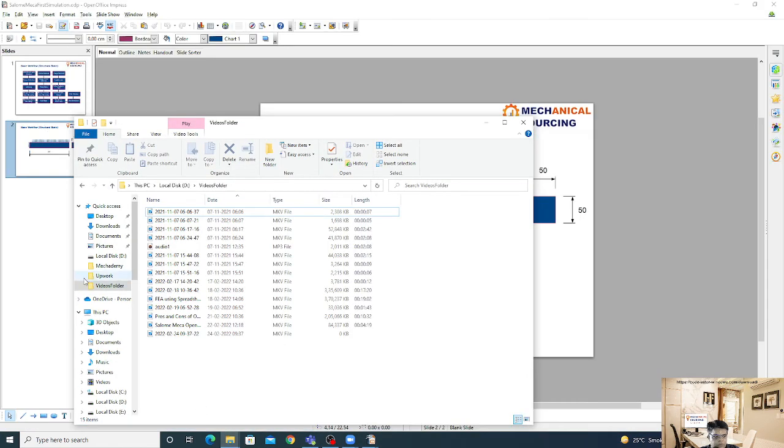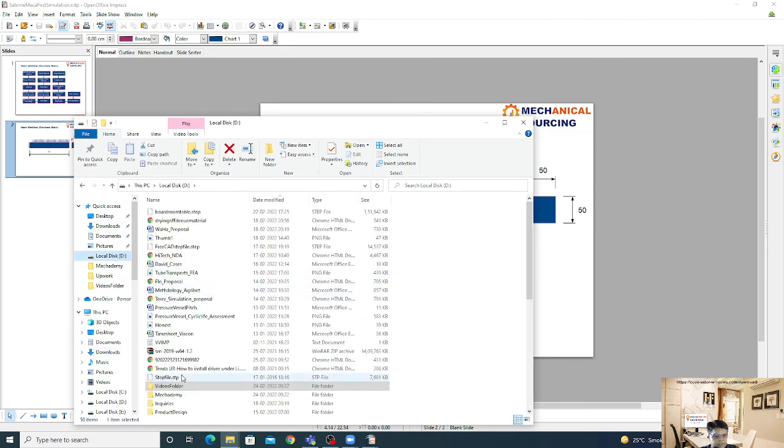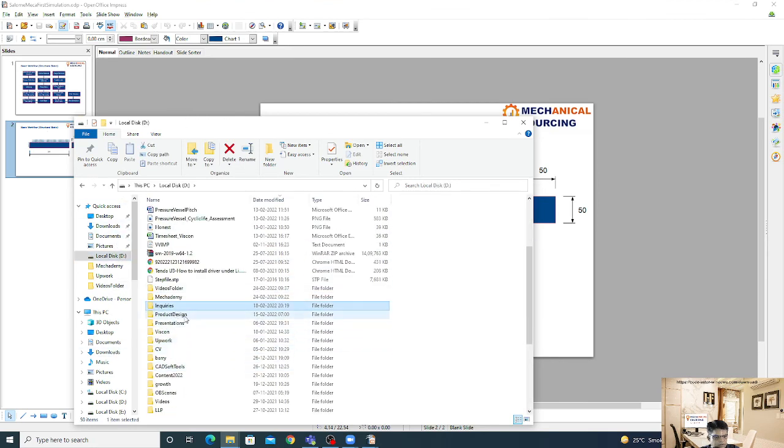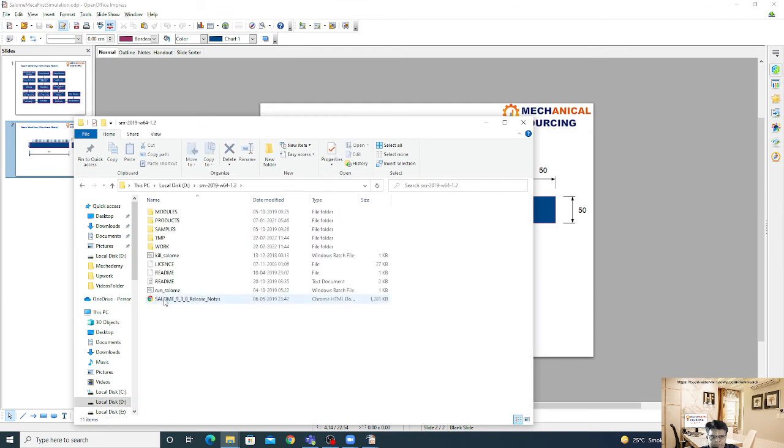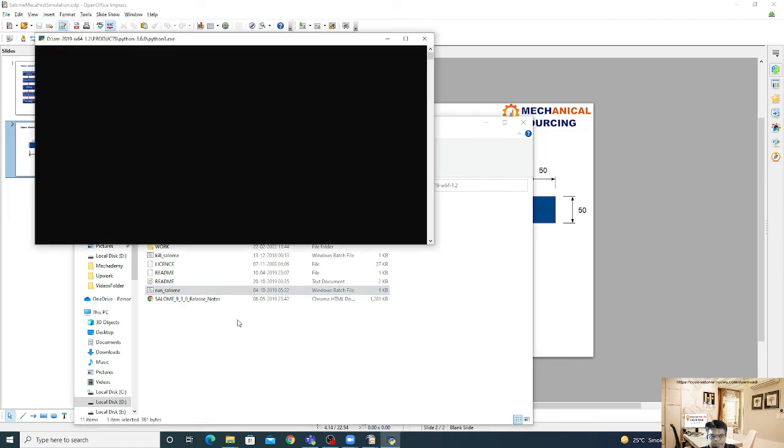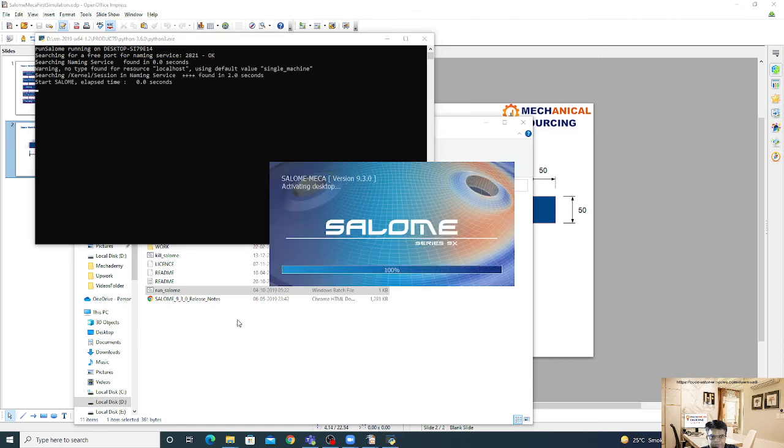First I'm going to open Salome Meca. In my system, it is this folder SM 2019 W6412. So run underscore Salome is the command. I am just double clicking it. And I believe that you are also doing it in parallel by watching this video.